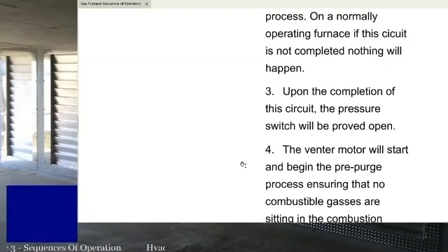And on most furnace modules these days, it has a blinking light, right? And it'll kind of tell you where to start. And a lot of times the pressure switch closed will be one of the blinking lights on there. But if they don't give you that diagnostic code, then you have no idea what's going on, nothing's running and you don't have power to your fan motor. It's the pressure switch stuck closed. So that's one of the most important things to remember. If it's using a pressure switch to prove induced draft, that pressure switch always has to prove open before it starts running and then close after the fan motor starts running.